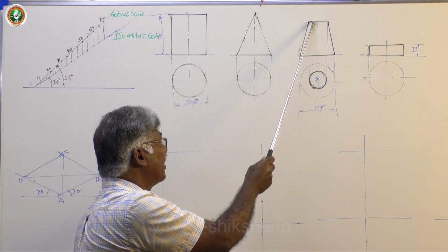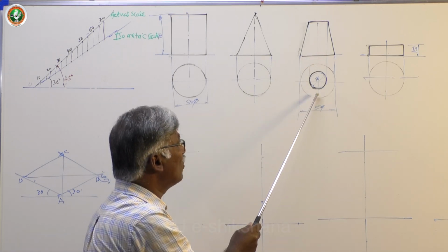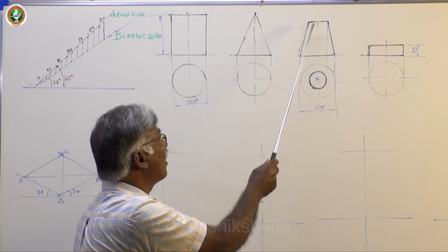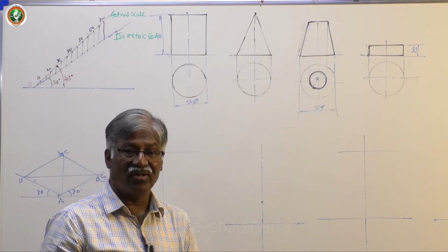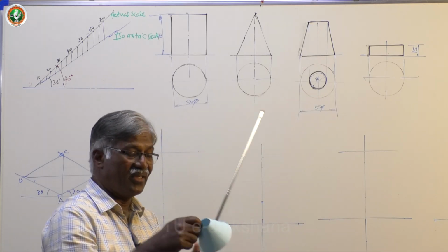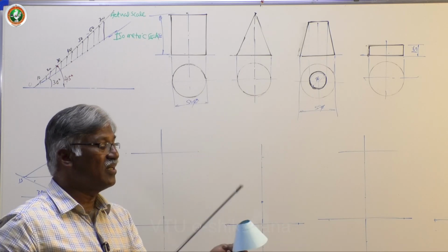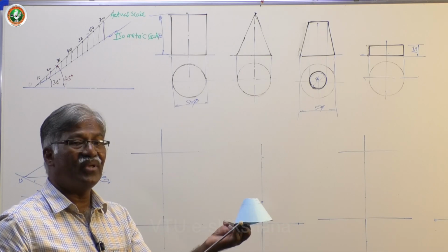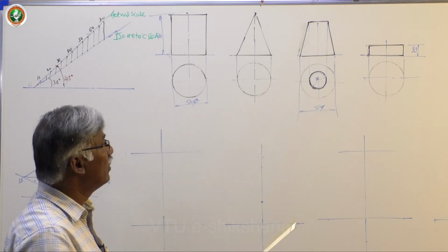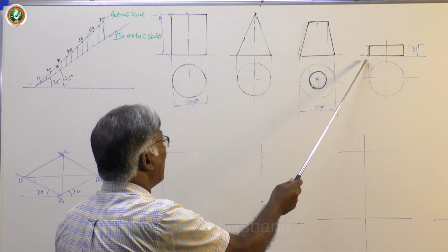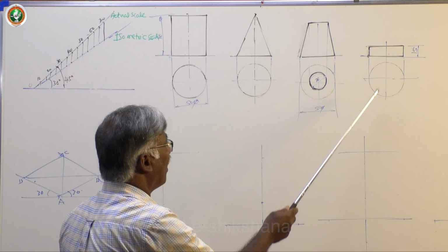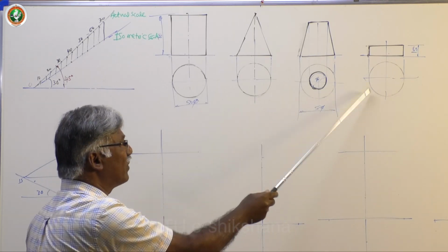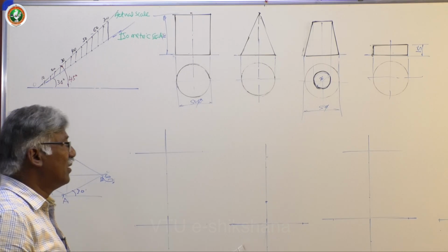Here also you can take around 60 mm height and also the outside circular concentric circles which represent the top view of the frustum of cone, and here this is 30 or 20 whatever and the base is 50 mm. Now the height is referred to as thickness here, it is around 15 mm, 20 mm whatever and also 50 mm dia. Now how to draw this?